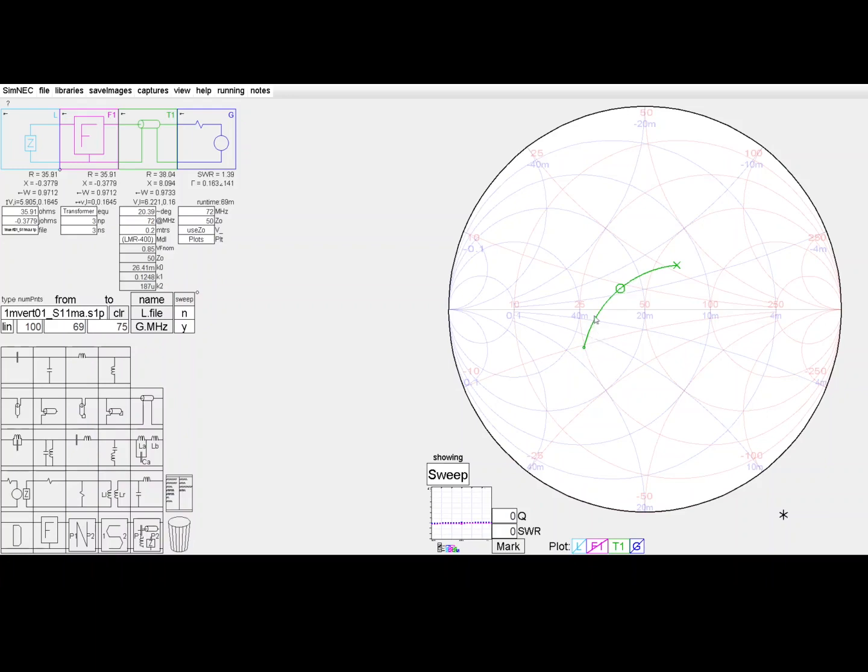So this arc is a signature, if you like, of the series resonance, but it can be rotated and appear in a different orientation in angular terms on the Smith chart. Now, about this rotation, one of the things to remember is that for every 1 degree that we add of transmission line, it rotates the pattern on here by 2 degrees, because there's a go and return propagation delay on the transmission line.